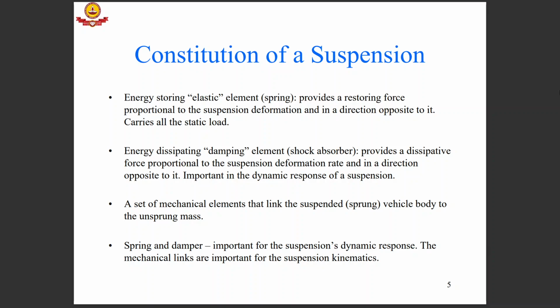The reason why we have an energy dissipating element is because the energy imparted to the vehicle by the road as the vehicle is moving on the road has to be dissipated so that it does not reach the driver, right? So this provides a dissipative force proportional to the suspension deformation rate, right?